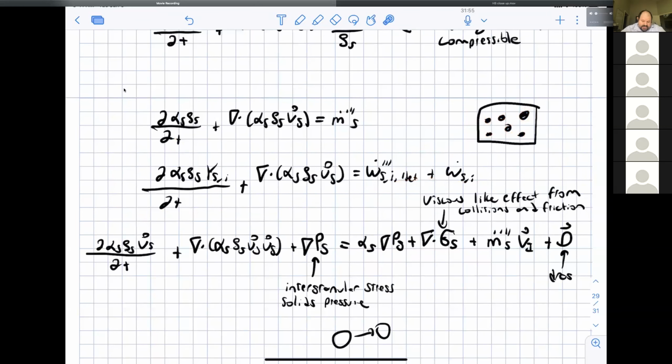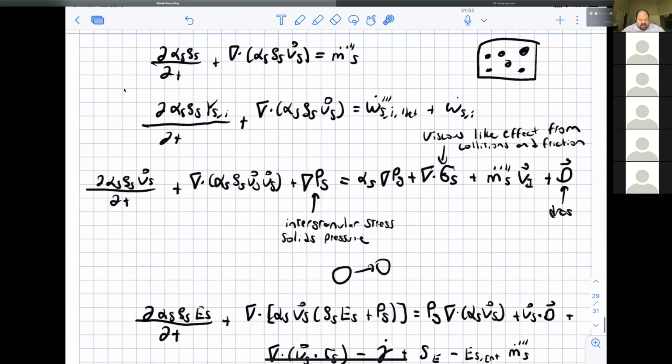Okay, and then there is a conservation of momentum for the particles, which is very similar to the conservation of momentum for any of the other models, except that since we have actual particles here, we have to explicitly include drag models. Again, Bala's group is a world-renowned expert on picking those and developing them, and I will refer you to his multi-phase flow class for how to model that. There are any number of these, some good and some bad.